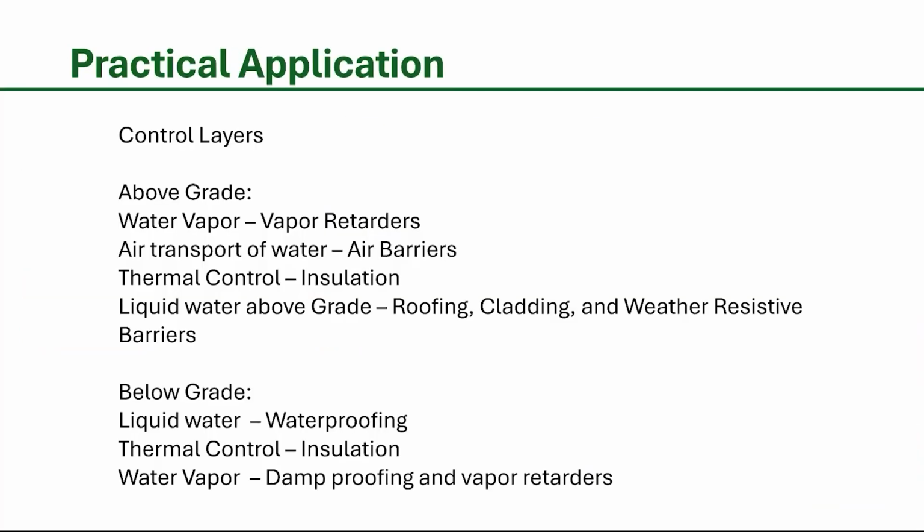So let's talk some practical application about control layers. We're going to manage moisture with control layers. Above grade, we're going to use vapor retarders to control water vapor. We're going to control the air transport of water using air barriers. For thermal control, we're going to use insulation.